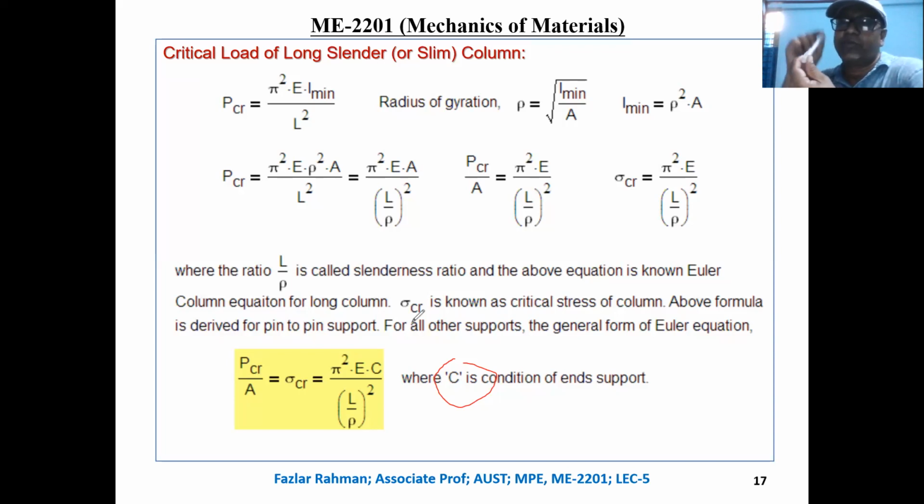But it can rotate. That means rotational constraint is not there. This pin support cannot say, hey guy, you cannot rotate, because he is weak. He only says you cannot move in Y direction, you cannot move in X direction. But if I hold it with my fingers like that, then I cannot turn it because it has some rotational constraint. This is a fixed support.